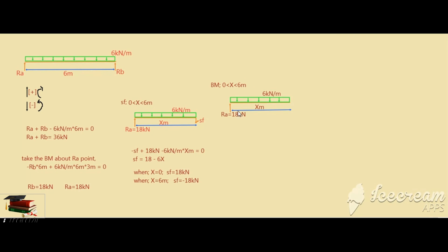Okay, this is the beam section relevant to this range. Now I am going to mark the bending moment for this section. So my bending moment point is this point. So I will mark the bending moment like this. Then according to the sign convention, I can write the clockwise moment minus anti-clockwise moment is equal to 0.